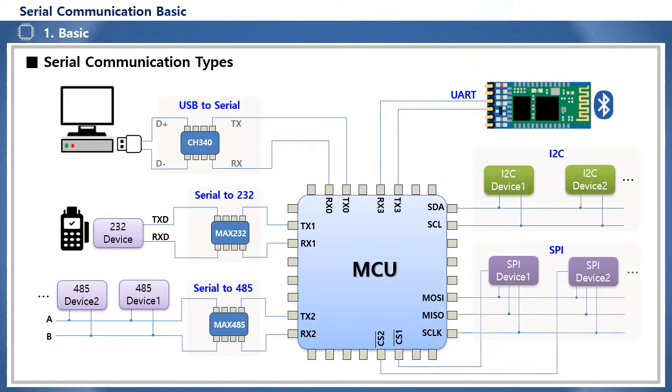Most of these communication ports adopt serial communication standards because, in situations where the number of GPIO ports on the MCU is limited, controlling devices in a parallel communication manner requires multiple ports, which limits system expandability. For example, even if only one 8-bit or 16-bit memory is interfaced, 8 or 16 ports must be used, which may result in a lack of ports for connecting other devices.